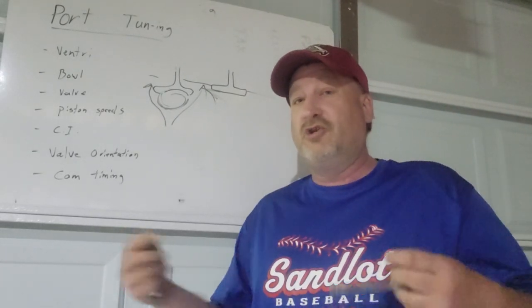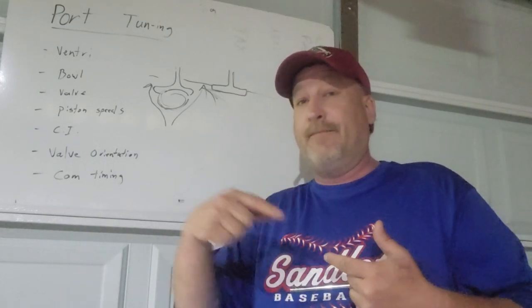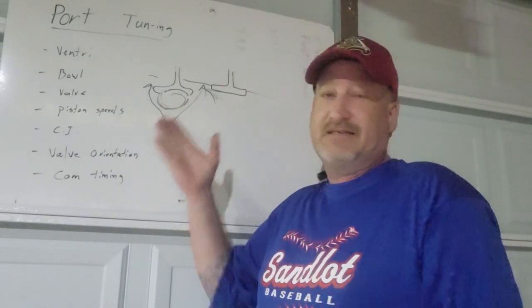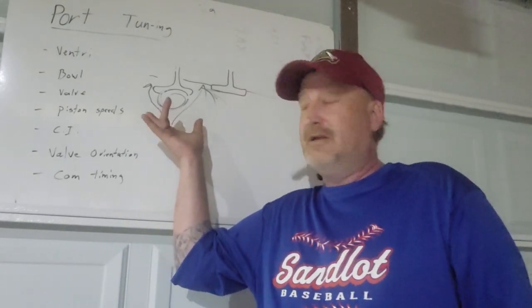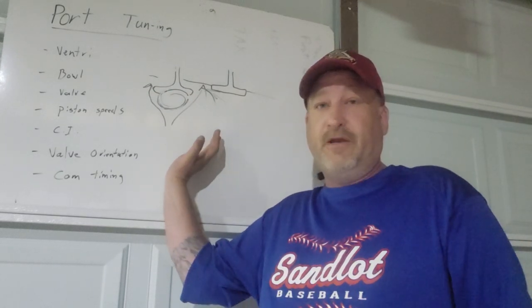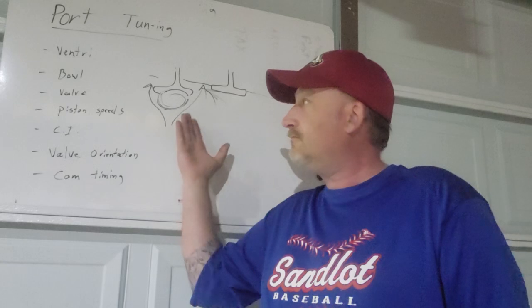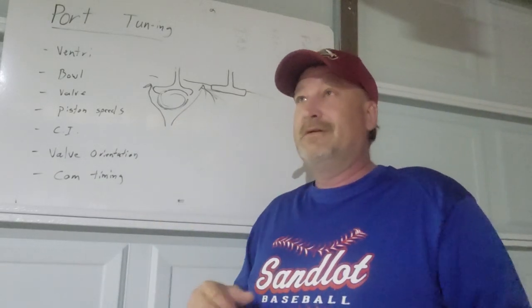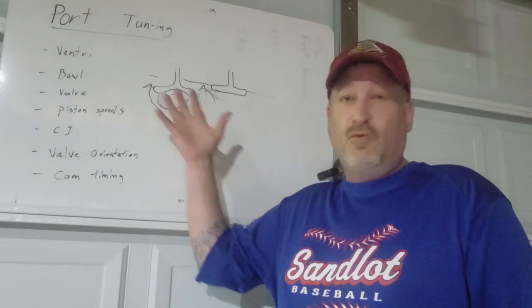So anything you can do to reflect any of the reversion coming back will allow your exhaust system to be more efficient, getting rid of the initial exhaust gases at low lift numbers, and then also helping the lazy air pressures as the piston is coming up, that other 15 to 20% of the exhaust air movement.